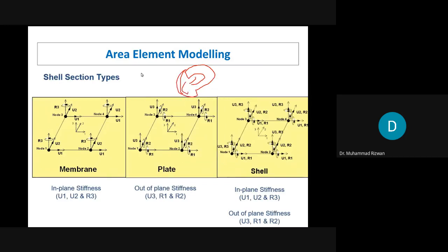So the loading which is actually applied because of this water or any gases whatsoever, it is like trying a pure bending type loading to this pipe or whatsoever. Okay, a pipe like this, for example, and so the stresses that this will develop will be something like this. So they will try to create a pure plate type behavior, where you will be having those bending type stresses. But if the thickness is very large, then the shear deformation of the section will also participate. Then you need to consider that as well.